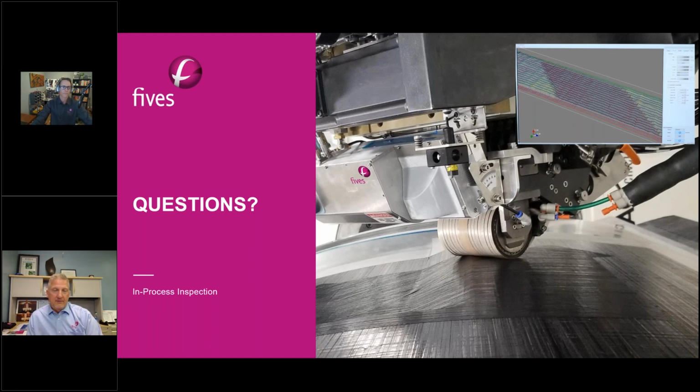What sort of dimensional tolerance can it measure? Gil, I'll let you have that one. Yeah, so I alluded in the slide, there's different features that have different tolerances. For gaps and overlaps, that's typically measured in a width. And right now, our resolution's probably down to 5/1000ths of an inch, but we like to be conservative and say about 10/1000ths of an inch.